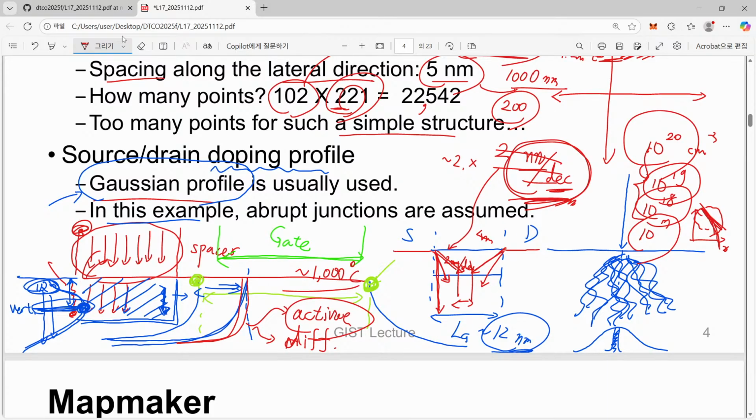Within a very short time, on the order of seconds, we increase the temperature from room temperature to 1000 Celsius. After a few seconds, we cool it down. It means that they have sufficient energy to take their desirable atomic position inside the silicon crystal, but they have no time to move or diffuse over the entire silicon crystal system. So that is what we do.